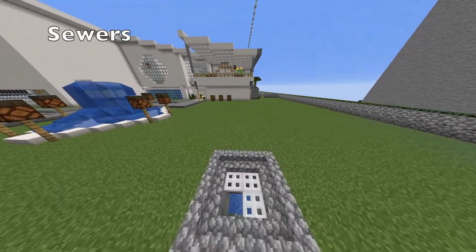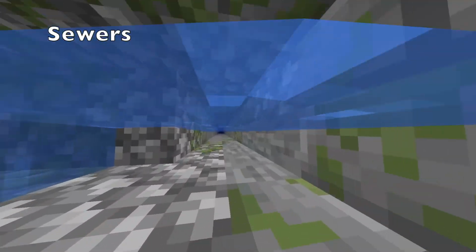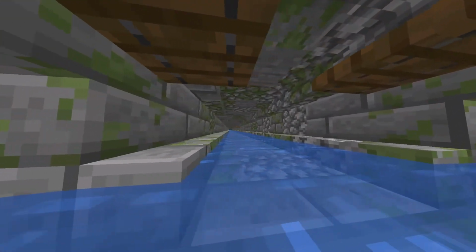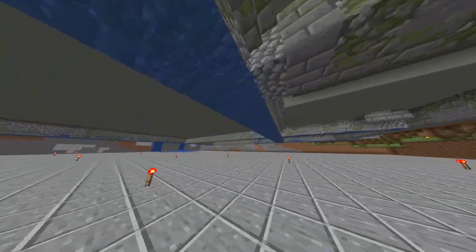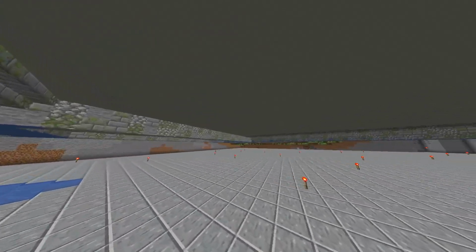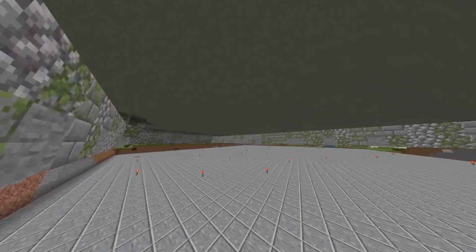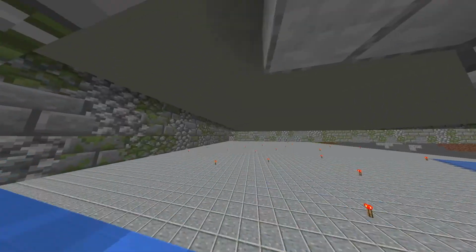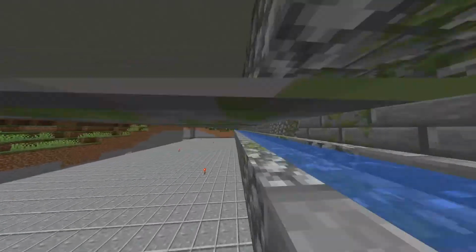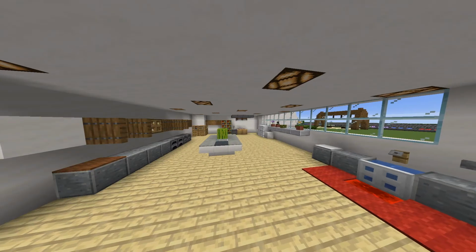The house contains a sewage system below. It collects the human waste and transfers it to a waste treatment center. Basics states that house owners should reduce their water usage by 40%. Keeping this in mind, we decided to put in measures that would result in less water use. These include having the sprinklers turn on during cooler parts of the day to prevent water from evaporating, and saving rainwater to use for the water mills, watering plants, and flushing toilets. This also includes small measures such as shorter showers and fixing leaks immediately.